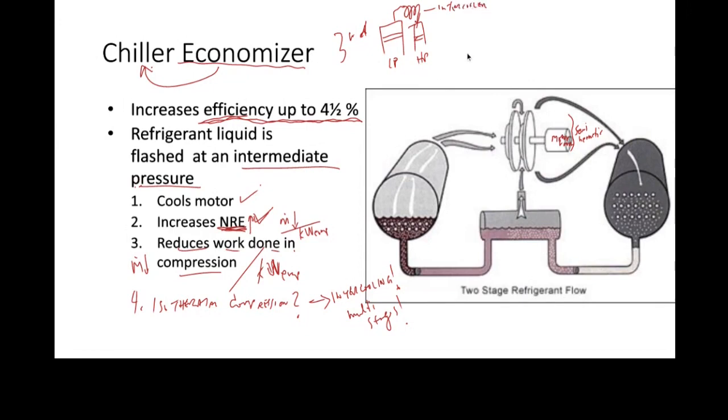Well, the refrigeration is really, really neat because we don't need cooling air, we don't need cooling water. What we can do with refrigeration is directly inject the refrigerant into the gas. Okay, so this would be like a non-contact intercooler, but we are going to be using what's basically a direct contact intercooler, which is extremely important.